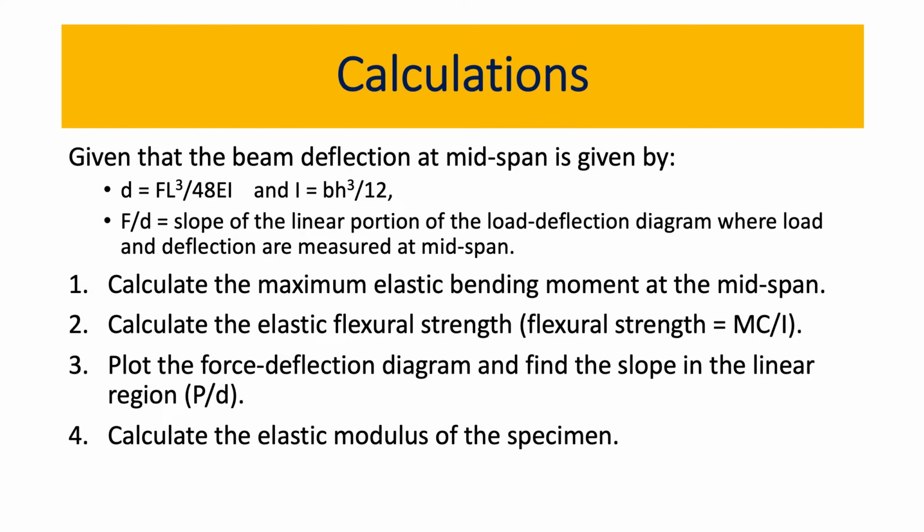In your handout, you were asked to complete the following tasks. So you need to calculate the maximum elastic bending moment at the mid-span. You need to calculate the elastic flexural strength. This is the formula for it. You need to plot the force deflection diagram and find the slope in the linear region, P over D, which is F over D, actually the force over deflection. You need to calculate the elastic modulus of the specimen. So I'd like to go through this one by one and just explain what you need to do and how you can do it.